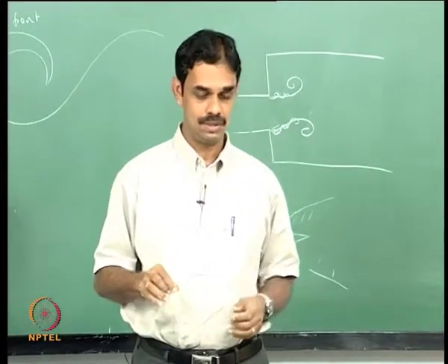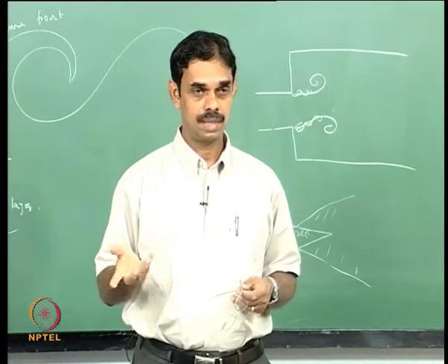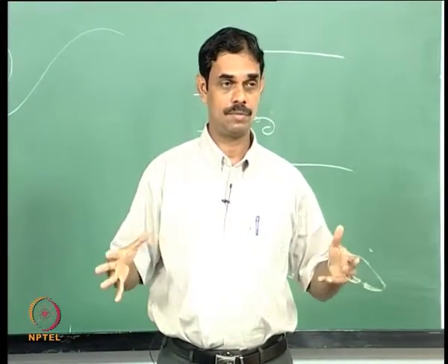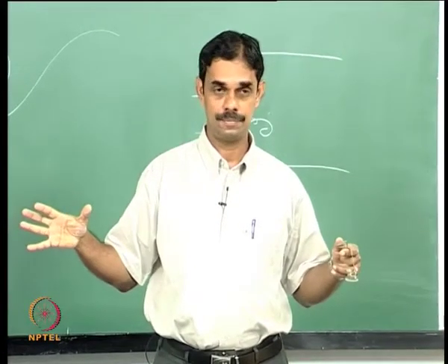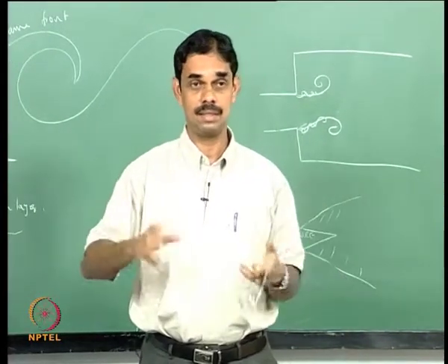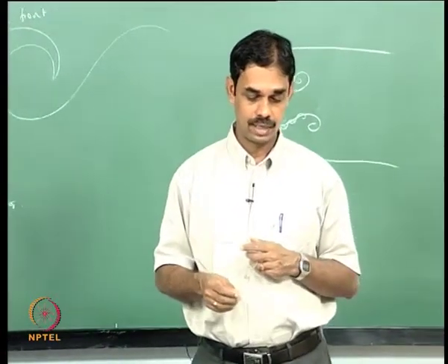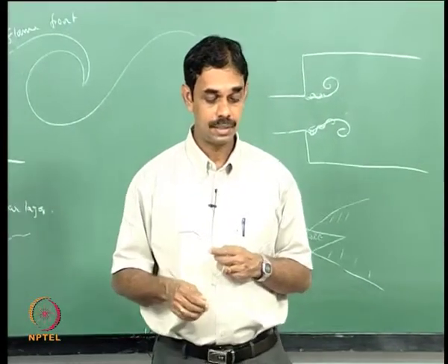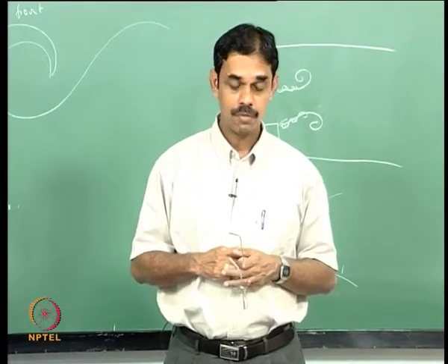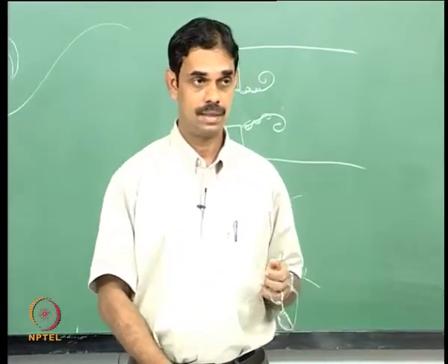So if you have relatively short length, then the vortex will interact with the exit nozzle. If the combustor is long, by the time the vortex reaches the exit nozzle, dispersion would have set in and the vortex would have smeared out and lost some of its coherence and spread out. But if the nozzle is close to the inlet, that is the combustor is short, then the vortex will still maintain its nice coherence and come and impinge on the nozzle. At that time the strong mixing between cold reactants and the hot products will occur after the vortices impinge on the exhaust nozzle, creating small scale vortices, and this would be followed again by intense heat release in a short time, and if it is in the right phase it can add instability.